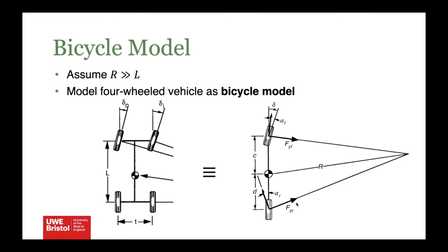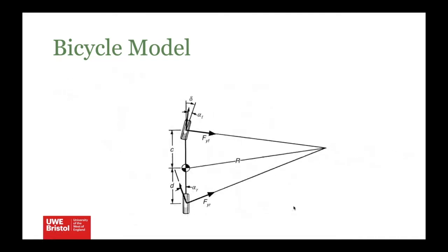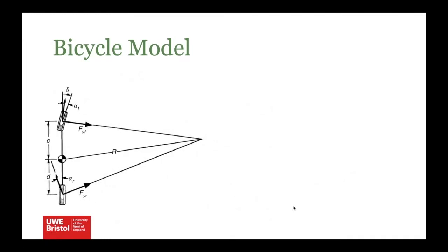Okay, so that's known as the bicycle model, and we'll refer to this model a couple of times, but this is the way we work this stuff out. And remember that these tyres in the bicycle model are representing two tyres. Okay, so you'll see some twos pop up in the equations when they may not, and that's because when you're working out the stiffnesses, often the data will be for one tyre, and you need to multiply that by 2 to get the actual force being generated. So we'll cover that in a minute. Anyway, so there's the bicycle model.